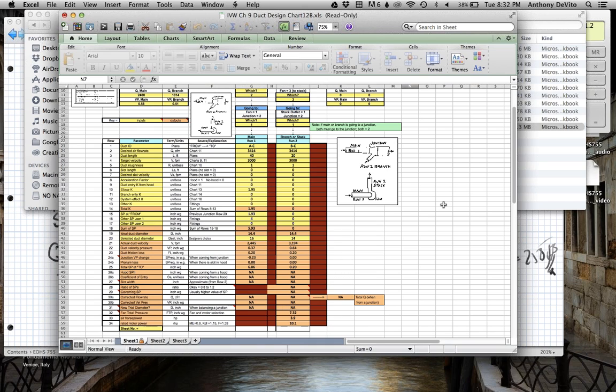Yeah, absolutely. So they're going to be a lot more. In other words, 100 feet per minute on that hood: if that hood goes up like 2 feet and it's 6 feet wide, that's 12 square feet times 200 feet per minute or 100 feet per minute. So your Q is going to be a lot larger than this.